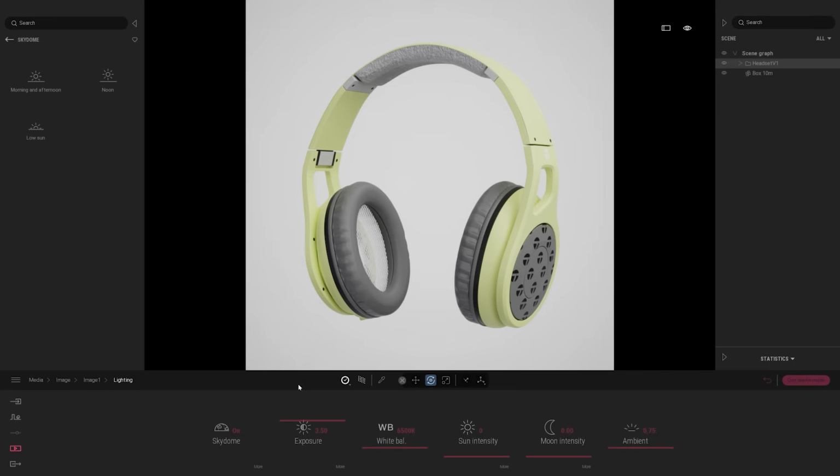So now let's actually start working on some materials. Twinmotion comes with hundreds and hundreds of materials, but right now they are dedicated to the architecture industry. So in my case, what I did is I took some textures from the Grayscale Gorilla website, and I created my own custom materials that I then saved inside what we call the user library.